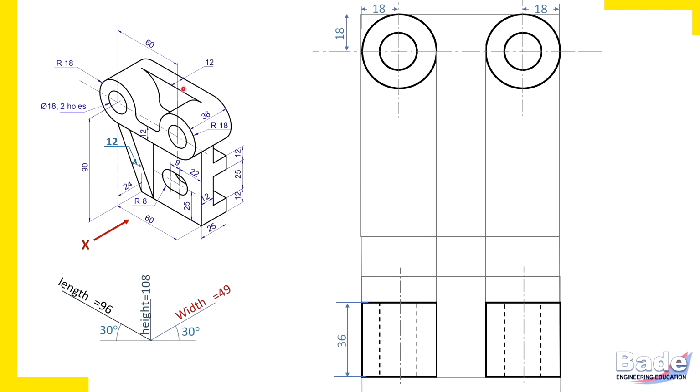This plate, which has certain shape. Okay, so we'll try to construct these two plates. This plate, which is vertical plate, this particular shape will appear in the front view. But this plate, which is 12 mm thick, will appear as a thin strip of thickness 12 mm measured vertically. So this top edge is tangent to both the circles. Then this bottom edge tangent to both the circles.